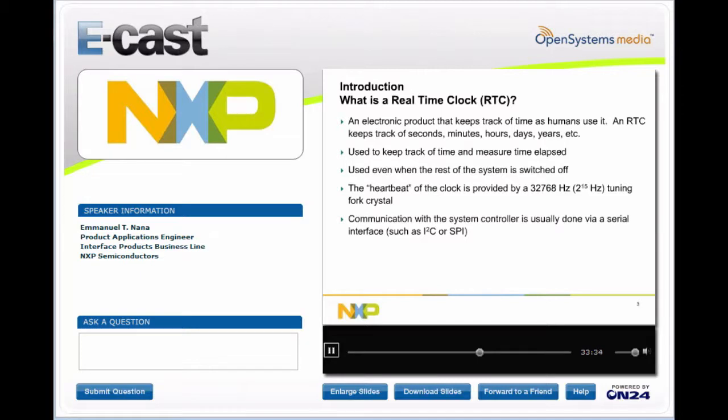from the environment. And within those systems, sometimes the power consumption either within the battery or the power storage device may be very low. We're talking about as low as 5 or 10 microamp hour here. So basically, in those applications, the NXP's real-time clock devices, because they consume very low current, are very suited for these applications because you can use that energy harvested power to power the NXP's real-time clock, and the device will still maintain its timekeeping function for a very long period of time.